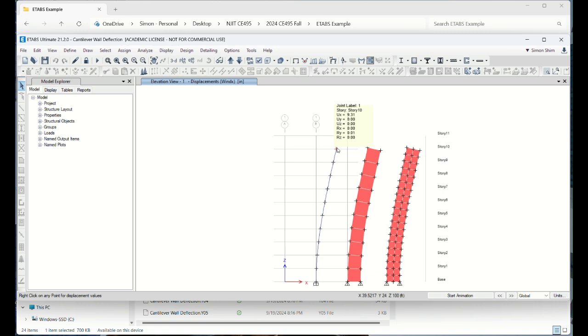Line element somehow has a tendency to overestimate the deflection, right? This is finite element software. Internally, have you taken any stiffness matrix class? I think that's maybe graduate. But internally, line element, you need to acknowledge this because we're using line element with one support, everything is based on just one line. So internally they calculate the stiffness, the internal stiffness matrix of finite element. They estimate 9.31, slightly overestimate, than our theoretical number.